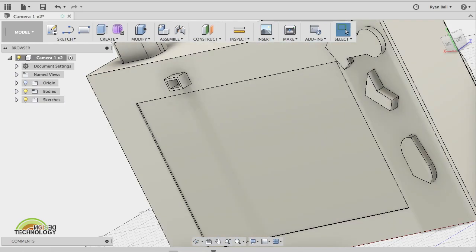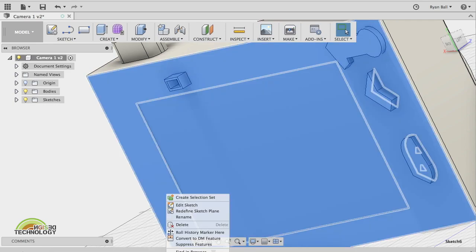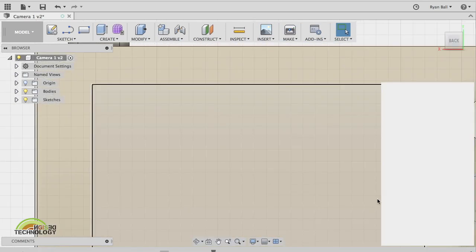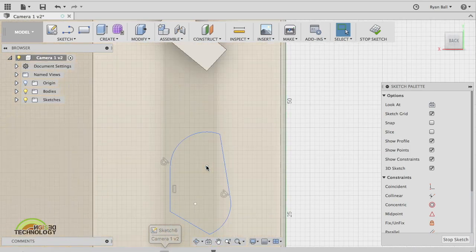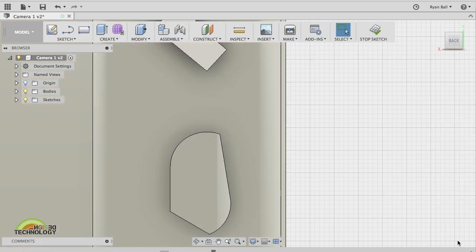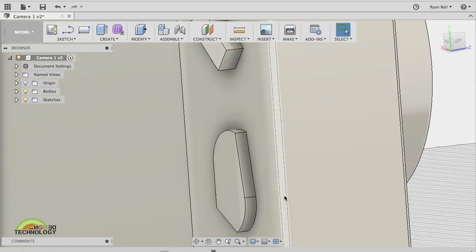I'll cancel that. The one before it is the shape. So if that is the extrusion, the one before it is the sketch, the shape that you did. So I'm going to choose which one. Let's choose that bottom one again. That sketch, I'm going to right click it and do edit sketch. It's now selected blue, and I can make changes to it that I need to. So I could draw another thing over the top, I could have a look at changing the dimension of it. When I'm happy, make the change and do it.